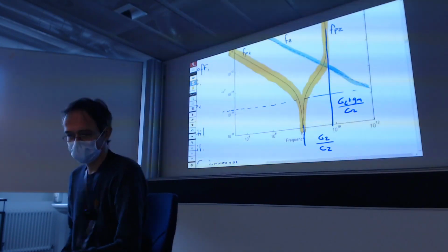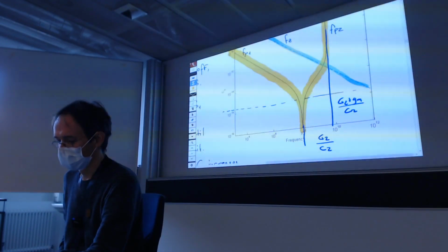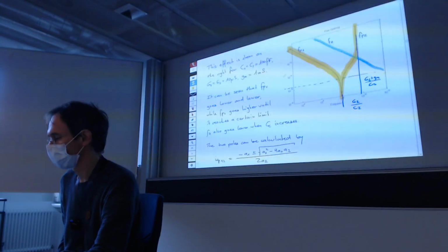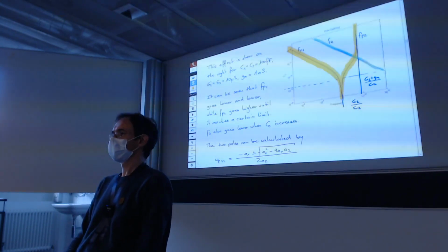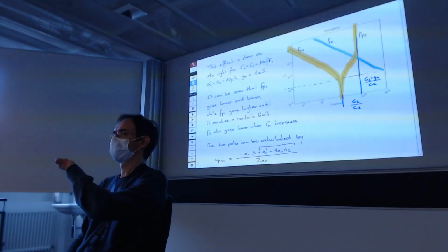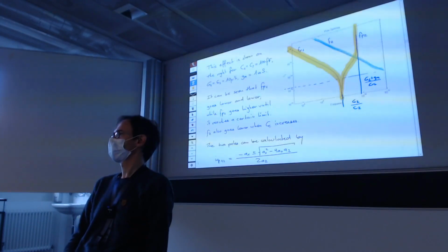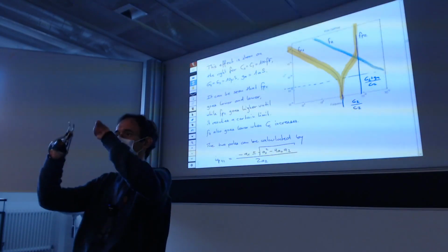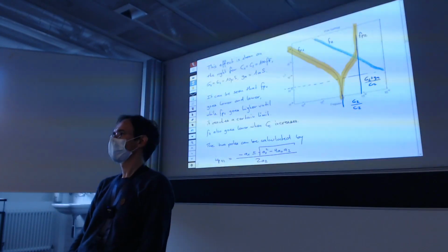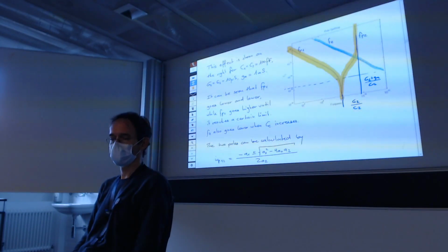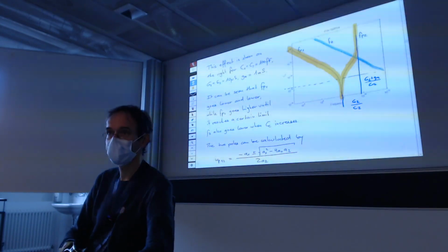This Miller effect, depending on how well you want to understand it, can be quite complicated. But the essence is simple. Just because you have a capacitive feedback between the output and the input of an amplifier means that the poles will split. And this pole splitting is used quite a lot in the stabilization of different amplifiers.